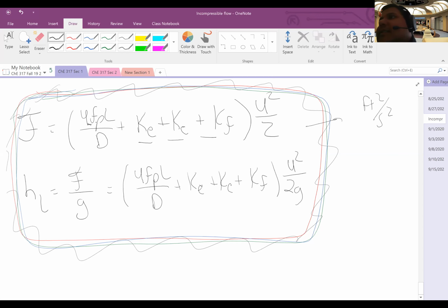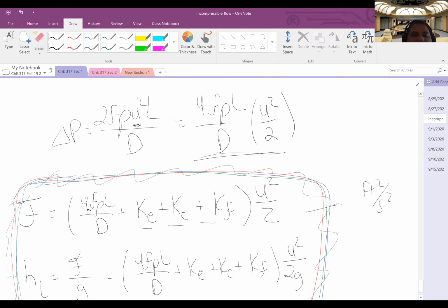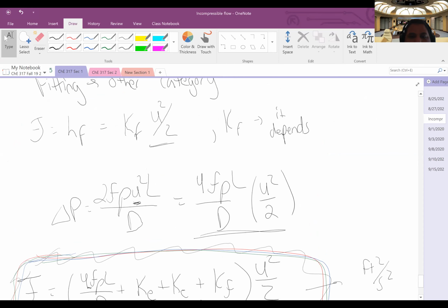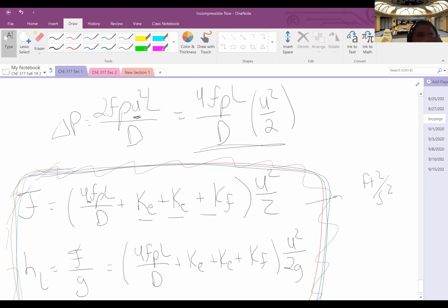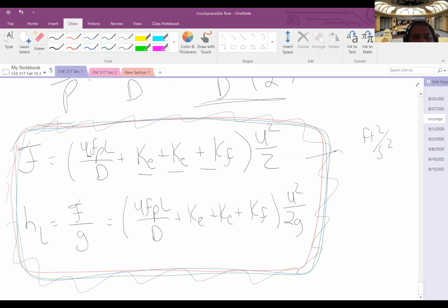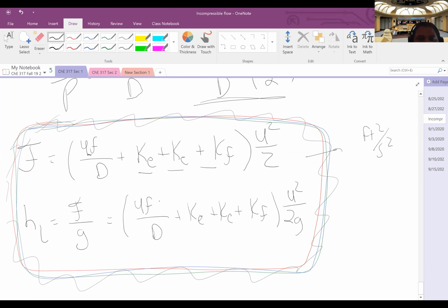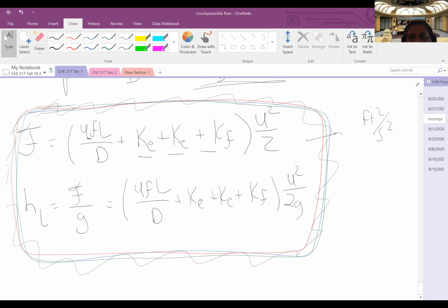Oh, you actually might have pointed something important out to me. We might have to change the form of our frictional dissipation to match it up in our system. So to get the units to work out, it needs to be in the form of delta P over rho, which means if we were going to combine it this way, we don't need to consider our density. Thank you for pointing that out. That was going to be a very important confusion for those. So if we do it this way, now the units work out.